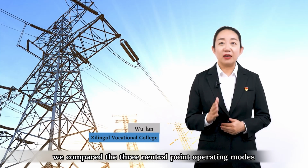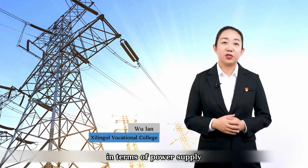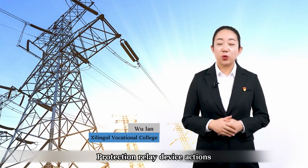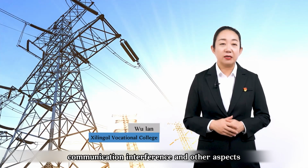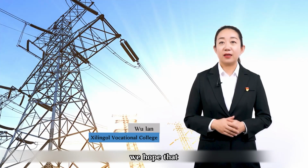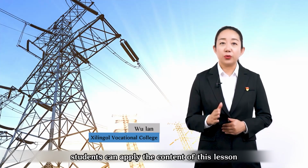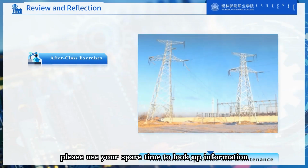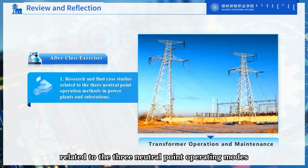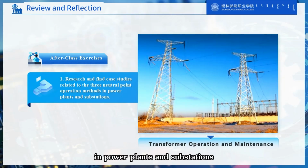In this lesson, we compared the three neutral point operating modes in power systems in terms of power supply reliability, overvoltage and insulation, protection relay device action sensitivity, communication interference, and other aspects. We also introduced the application ranges of the three operating modes. We hope that students can apply the content of this lesson to practical work cases. Please use your spare time to look up information and find some cases related to the three neutral point operating modes in power plants and substations.